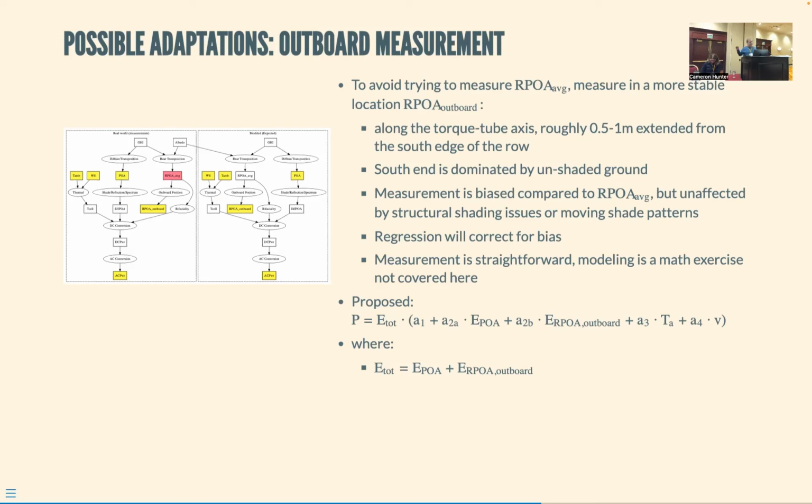And you put the same sensor at the end of the torque tube and see 130 watts per square meter. So clearly there's a concern about depending on that value being a representation of the average. But the out is that we're doing a capacity test. And the capacity test does this regression, and the regression can adapt and say, whatever's at that location corresponds to the power out.